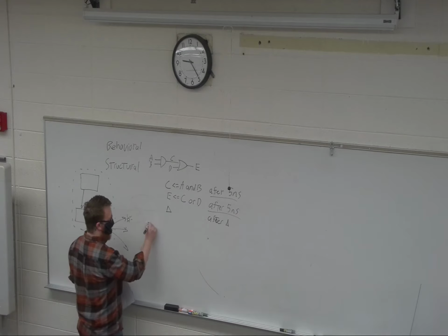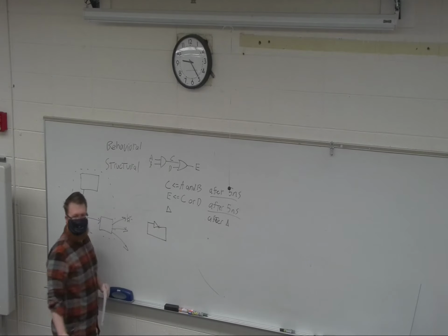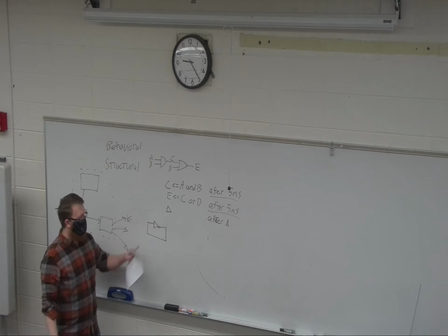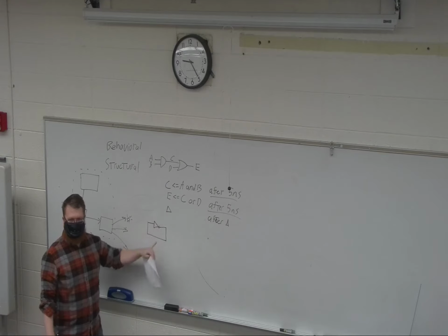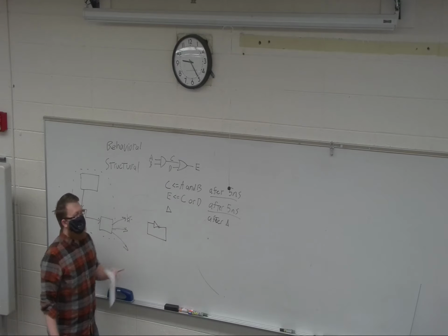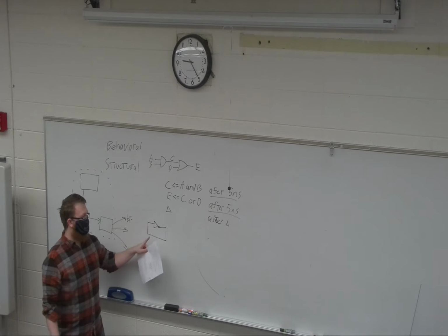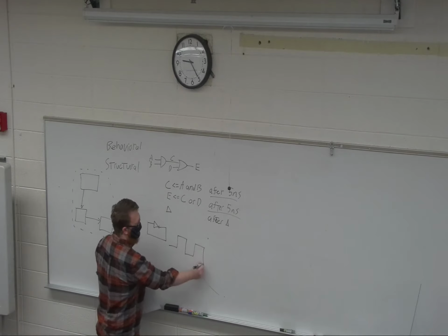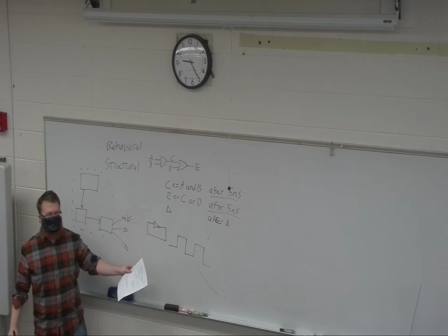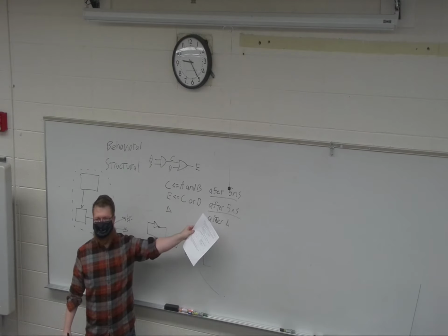This will matter for some types of circuits, right? The most obvious one is if you just have this as an inverter, right? A 1 goes here, that means it zeroes out, but then the 0 feeds back around and makes it a 1. So this is going to create an oscillator. And if you write after 5 nanoseconds, that's going to give me what output, right? It's going to go 0, 1, 0, 1. Oh, look, I've made a clock, right?